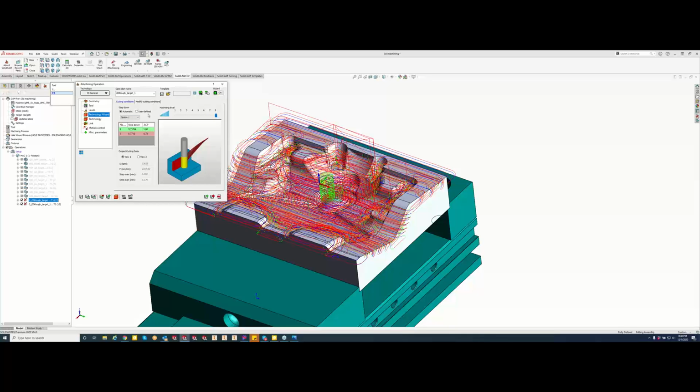So one thing I did want to show you guys too is with the control that you guys would like in there. You can come over to the modify cutting conditions, and like I said before, you can come in here and tell it, instead of a 0.07 millimeter chip thickness, I want something smaller, or maybe I'm worried about the horsepower that it's going to be requiring at the machine. And that's where I just remembered it now.